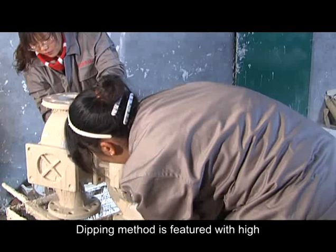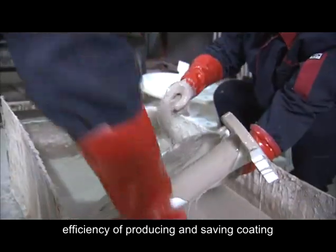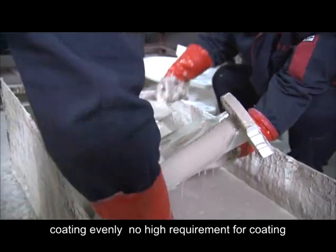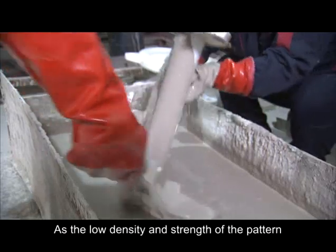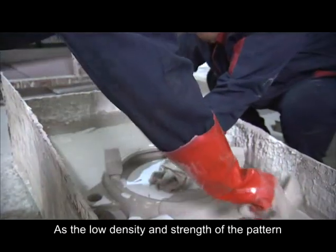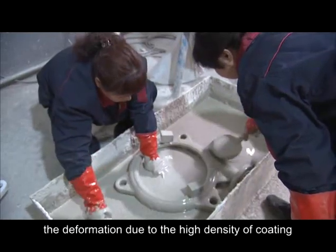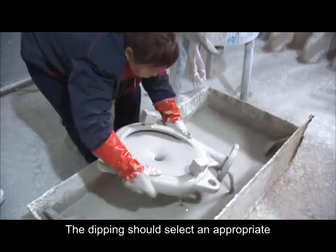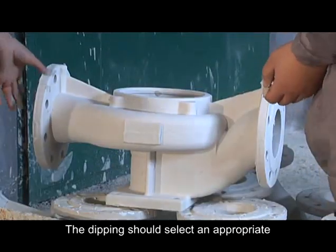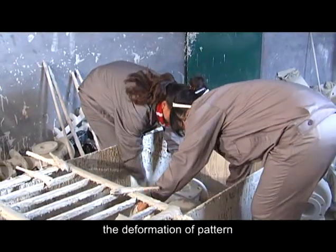The dipping method is featured with high production efficiency and saves coating. Coating evenly. No high requirement for coating and easy to operate. At low density and strength of the pattern, the deep coating should pay attention to preventing deformation due to the high density of coating. The dipping should select an appropriate direction to dip coating in order to prevent deformation of the pattern.